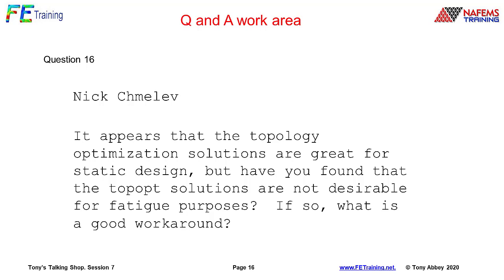Nonlinear would be a challenge, and I would see the evidence of nonlinear analysis coming through. As I said, dynamics is coming through very strongly. I've seen evidence of fatigue. The workaround would be, I guess, for fatigue to say let's minimize the peak stresses. But again, at the moment, it tends to be a global peak stress. You perhaps want more of a local peak stress. So that would be a good workaround at the moment.